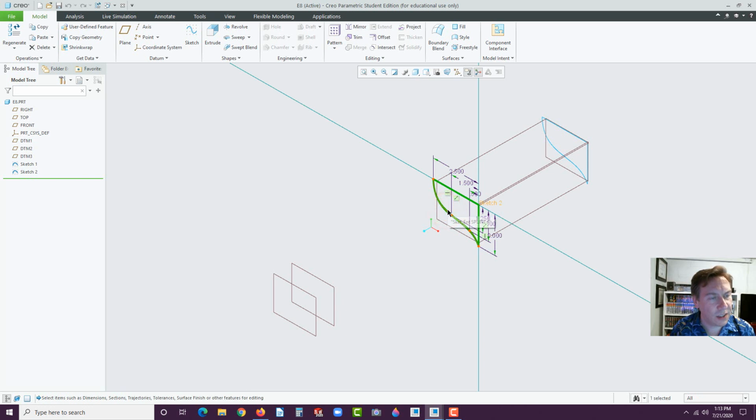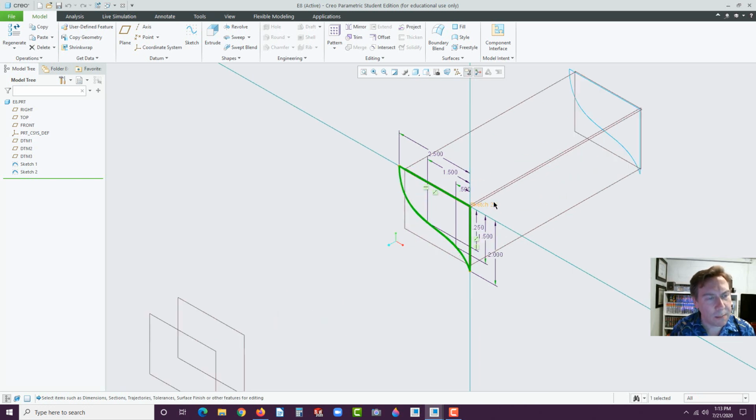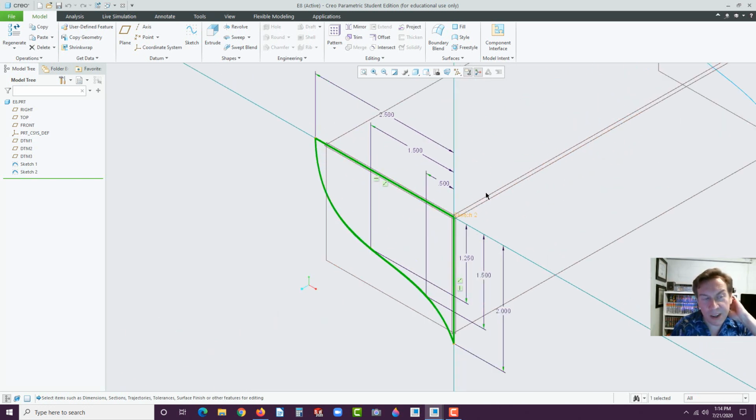Let's click on it. You can actually double click on it and the dimensions will appear. Now we could make changes to it. Now remember, it gets larger at this midsection. Now if you're not able to see these dimensions, that's okay. Just click on it and then go to the gold ball with a pencil on it to edit the sketch, and it'll bring you normal too, and you could change these dimensions the same way we're about to change them. It's going to be a little different here than it is in that environment, but if you could do it this way, this is really nice.